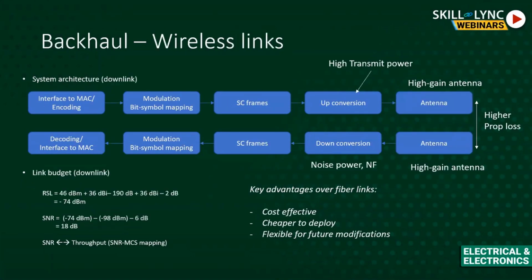Now when we switch to a wireless link, which is similar to what we have seen, except that now we have a really high gain antenna. This is not any user handheld device. These are devices that are placed on top of buildings or on top of towers, from one tower to the other tower. So there are two antennas there on both sides, because earlier, if you remember the link budget, we had a good 18 dBi gain on one side and less on the other side, right? Because the other side is always a user device, which cannot have a bigger antenna. Whereas in this case, both antennas are not user devices, and they are typically mounted somewhere else, maintained by a different company. So in that case, both of them can go as high as 36 dBi. These are like the highest possible numbers I'm showing.